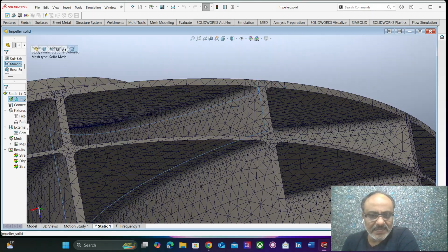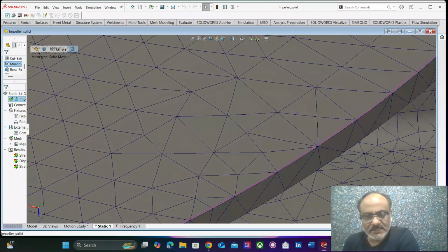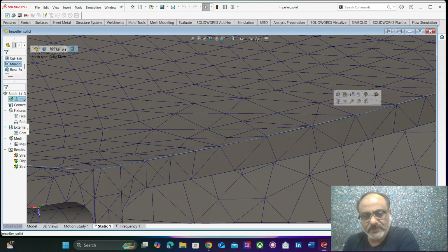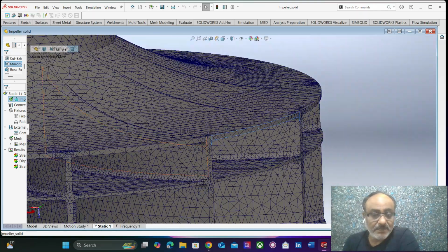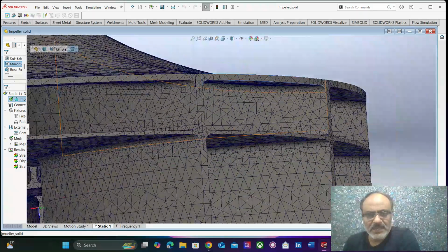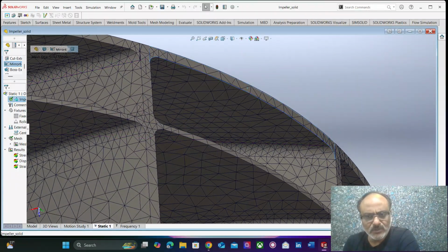So each element, whatever triangular entities you see here, these are all each solid element. We call it isoparametric tetrahedron elements, and these are well-defined geometries, and through the interpolated points we call nodes, these elements are all connected using nodes.